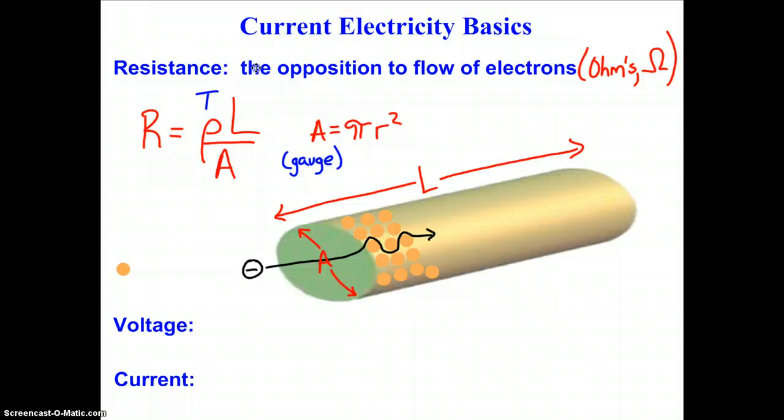Now, why is cross-sectional area inversely related to resistance? That kind of doesn't make sense based on our previous discussion with length. It would make sense to us that as the cross-sectional area increases, you're, again, putting more atoms in the path for the electron. But in reality, by increasing the cross-sectional area, you would be adding more paths for the electrons to be able to flow. So that's why that decreases resistance.